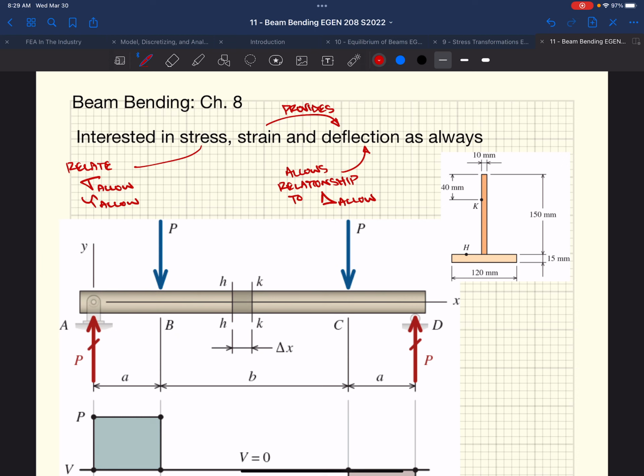It starts gaining water. Well, we put limits on the amount of displacements we have in our members in order to get away from that. Vibration is another thing, right? A lot of the buildings on campus have brick facades on them, right? Those facades span over doorways and windows and things like that, and we don't want brick to break or crack. And so in order to get away from that, they tell us that we can't have more than X amount of displacement.